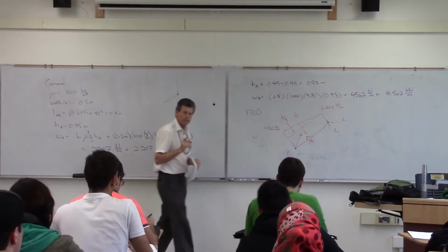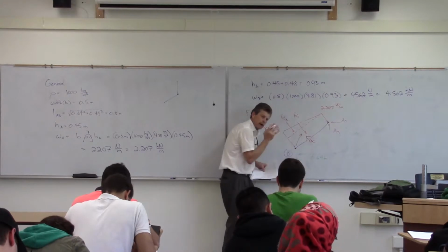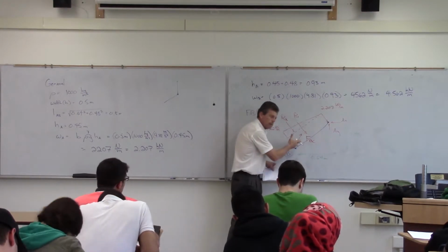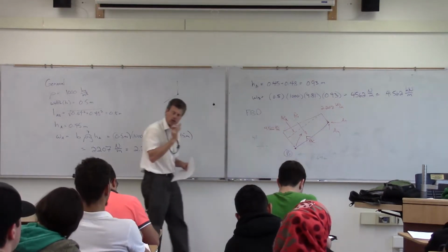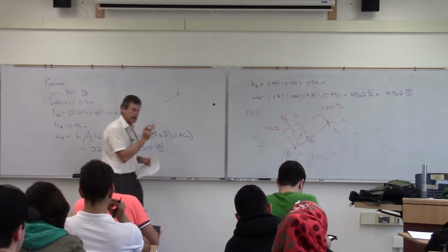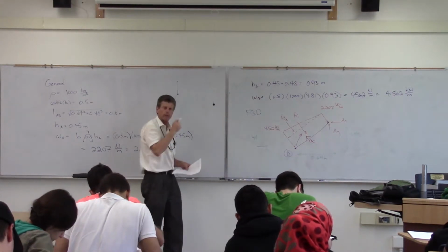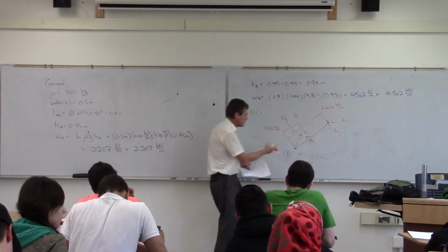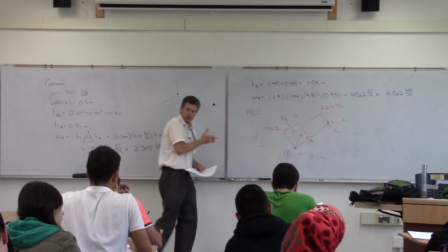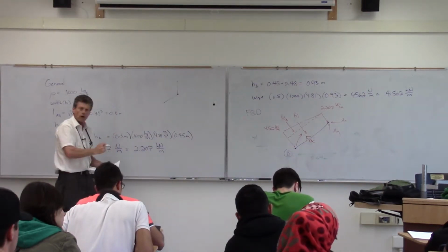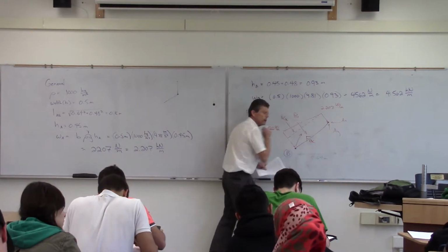Now, if that cable doesn't have any tension in it, we would have a force there at B basically resisting that. But what we've been asked now is, okay, what is the force of that cable just to open that thing? So at that point, when it's just opening, B is not going to be providing, that little penstock at the bottom there is not going to be providing any force. All of the force of that gate, due to the pressure, will be going into that particular cable there.